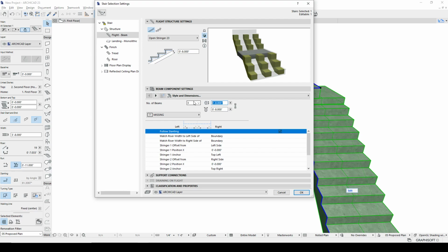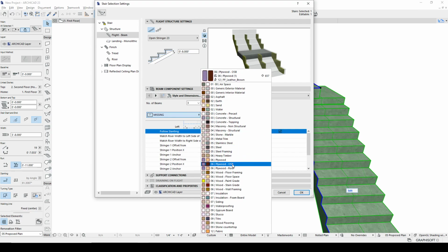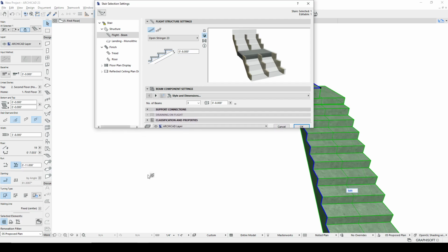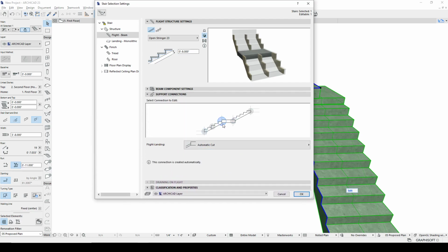And now it looks more like joist stringers, or stringers rather, that we'd make out of 2x material, 8 inches below the notches. Wood framing. This allows you to adjust exactly where those stringers are. Here you can adjust what these connections look like.